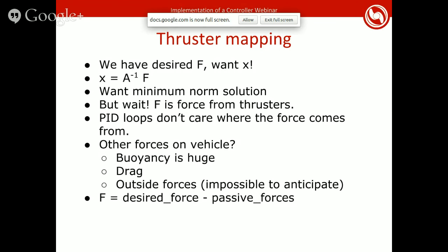You can't really do that. So what usually happens is that it becomes a bounded minimization problem, where you can make an objective function that is the error between your outputted force and torque and your desired force and torque, given what's actually going to happen with the thruster values.